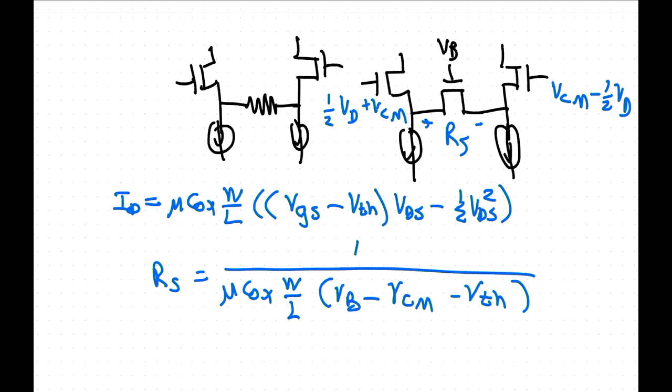I don't think so. If you want this to be linear, you have to apply a fully differential voltage across it. Otherwise, it's not linear. If you look at the difference current, it's fully differential, which means that by putting in the P device you're not really gaining anything, because you will have the same drain-source voltages in both of them, and they both have to be in saturation. So I don't think it helps.